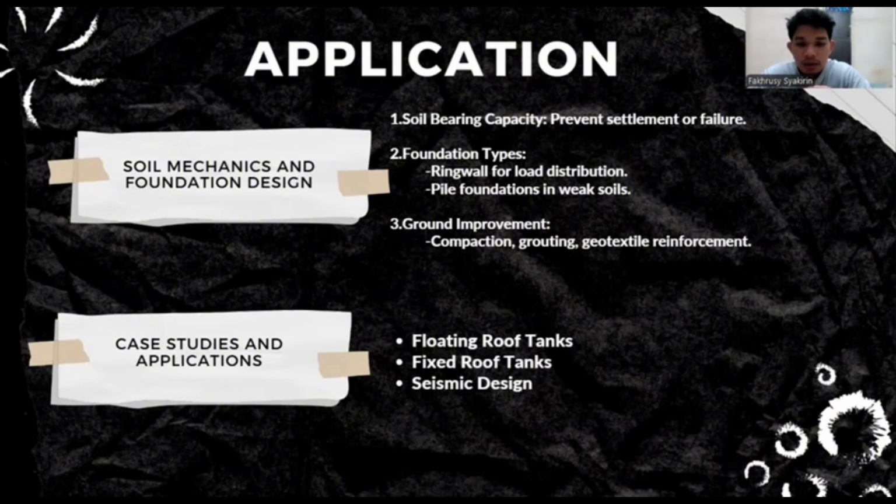Fixed roof tanks, on the other hand, must be designed to withstand varying pressure loads, both from the weight of the stored product and from environmental forces. Seismic design also integrates dynamic consideration with static analysis to ensure that the tank foundation can survive earthquakes and other ground movement.